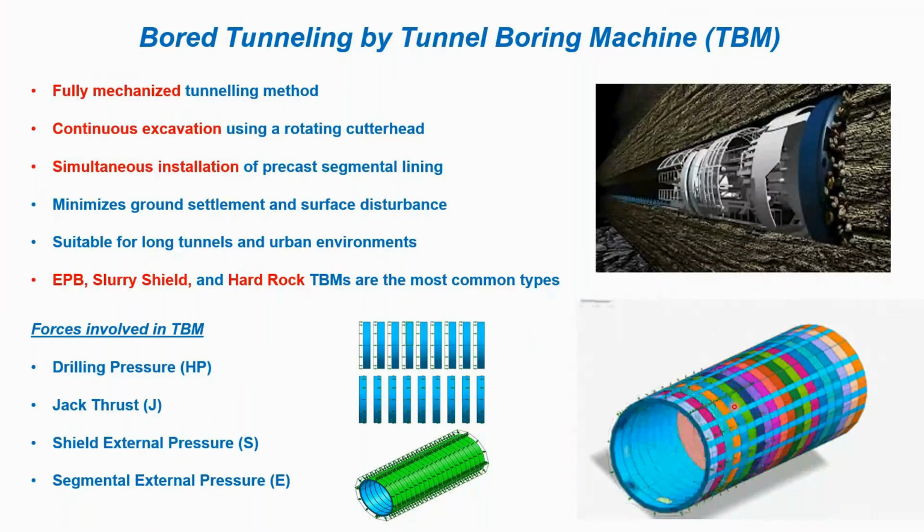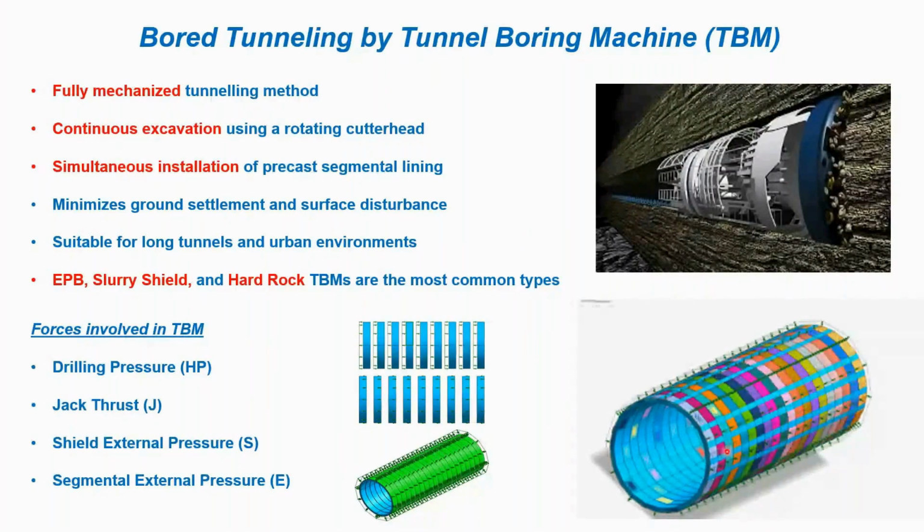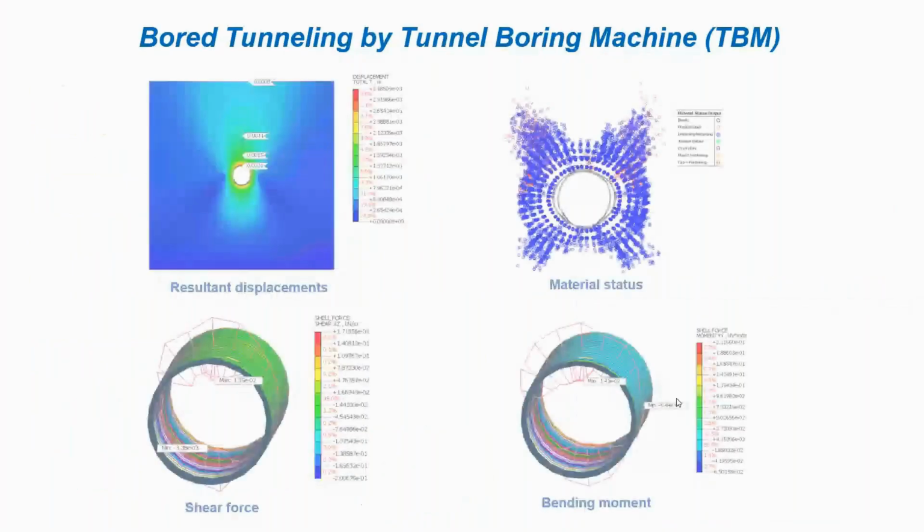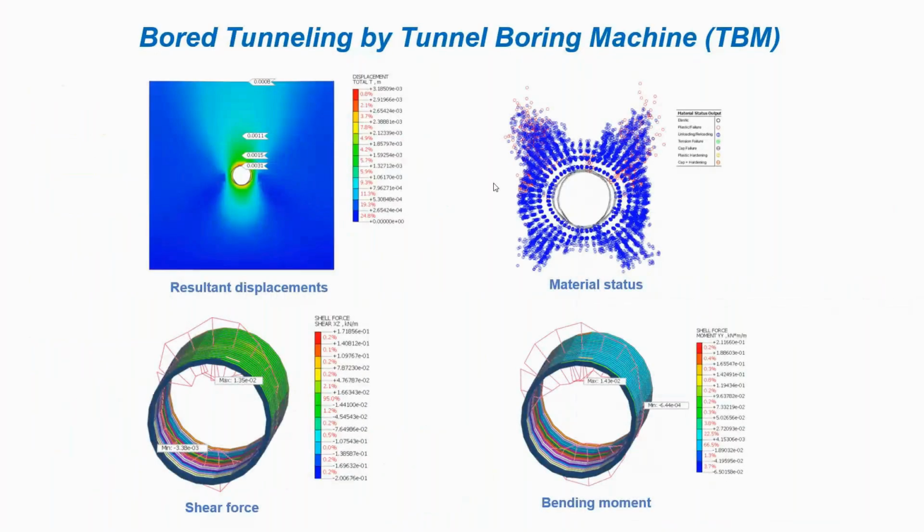And these are the forces we need to consider during the modeling. In this way, we can model the entire process of TBM tunneling. And in this, we may need to assess the results in terms of the resultant displacement or the other components of displacement. It generally helps us to assess the ground movements around the tunnel, identifying the settlement zones, and understand how the excavation affects the surrounding ground.